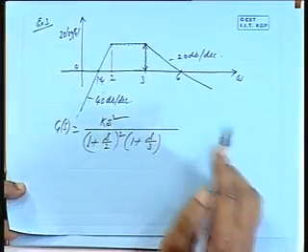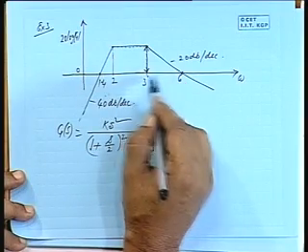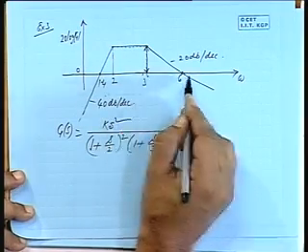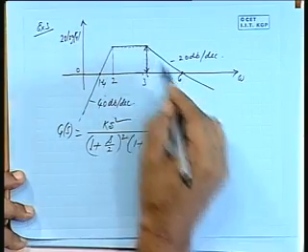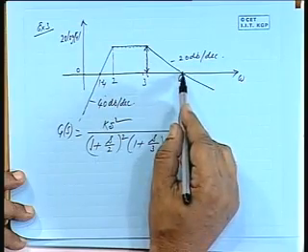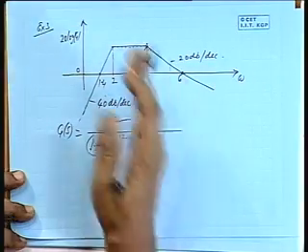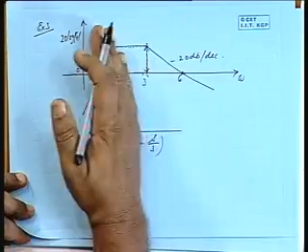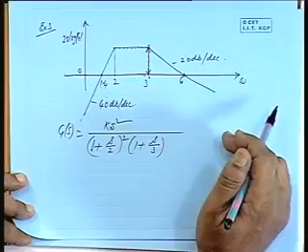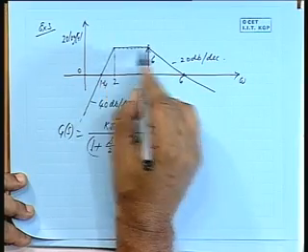Now tell me. Say 6 divided by 2 is 3. So basically you are going up like this. So what is the increase in this? In octave, 20 dB per decade means 6 dB. So from 0 it will rise by 6 dB. Or from 3, if I double the frequency, 3 to 6, it is having a fall of 6 dB. So this height is 6, because this is a horizontal line.